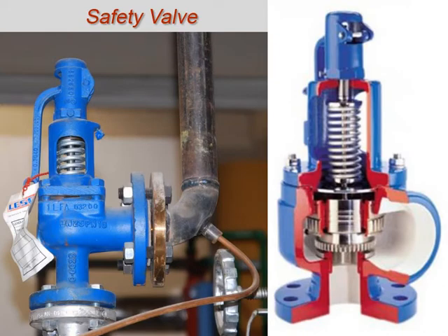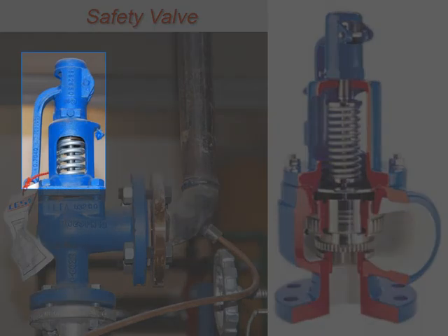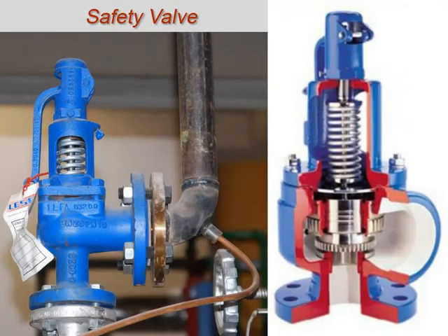Safety valves, on the other hand, rapidly pop fully open as soon as their pressure set point is reached. It will remain fully open until the pressure drops below the reset point. The reset pressure is a lower pressure than the set pressure. Safety valves are typically used for compressible fluids such as steam, air, or other gases. Safety valves can often be distinguished by the presence of an external lever at the top of the valve body, which is used for operational checks.